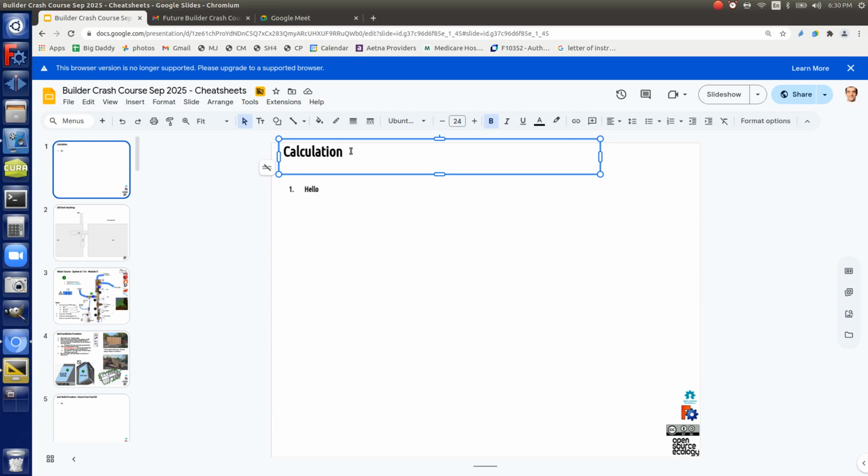That's what engineering codes do, they work off that conservative value, because while wood may be 1,000 PSI for high quality, number one grade lumber with no knots, regular wood they actually derate to 300. So with 300, we did it to the least value. And that's what they would say: that thing can hold 5,000 pounds.